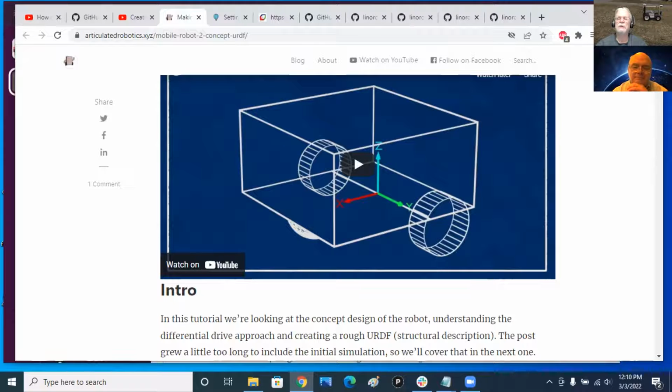So I believe the next option is, if you go back to the original stuff back when ROS 1 first started, they're giving tutorials, you have to have some way to tie these joints to some software that'll make them move. So one of the simplest things is, you've got this vehicle built, so you go into your URDF file and you add a block of code that says, I want to add a ROS controller.